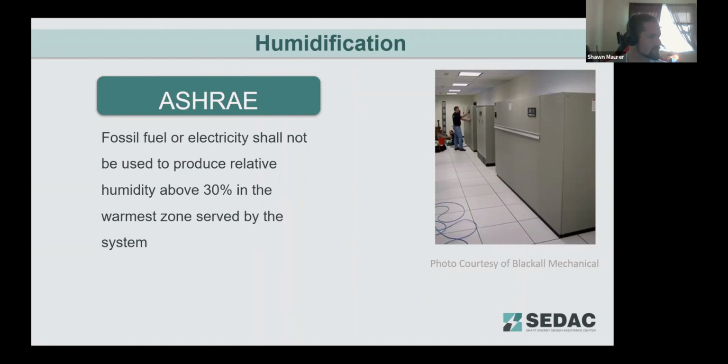But yes, you want to make sure that when you're doing these designs, the ASHRAE limits are giving you the widest band possible for allowing a little bit of design flexibility while still maintaining safety. So while that 60% is getting close, there is a lot of research that about 65% relative humidity is where that risk really goes up. At 60%, you're on that borderline where a lot of designers, for safety reasons, will go lower than that.